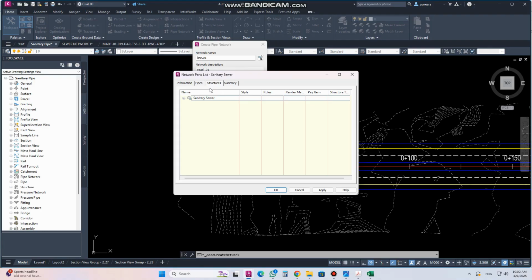when we are shifting water from the river to a manhole like this, we are using that pipe because the HDPE pipe is stronger than the UPVC pipe. So it's depending on the situation.